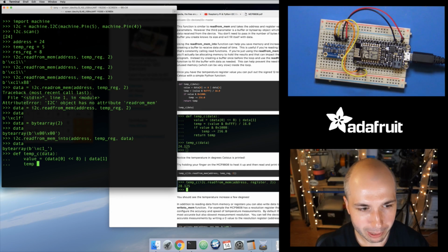Okay, and then now I'll grab the temperature as the lower 12 bits of data here. If I AND my value with 0xFFF, that's going to grab those 12 bits of data, and the sign bit is that 13th bit that we'll look at in a second. If I divide that by 16, that's going to do some of the conversion into the floating point value.